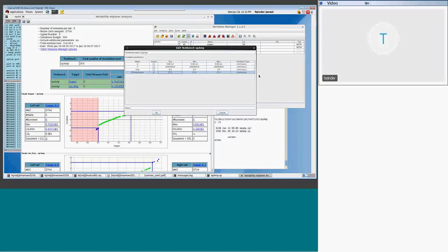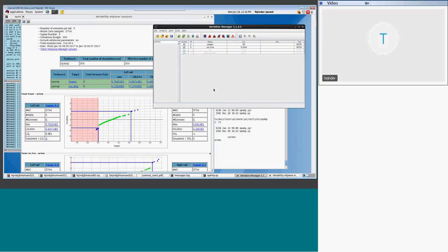So if you change this one and run it again, basically modify that, and as mentioned, it has the data increment, so it will increment accordingly. You can say, I need to run that at 27 here. I can change the temperature to something different, then update. After that, update the test bench, and then it will go again.